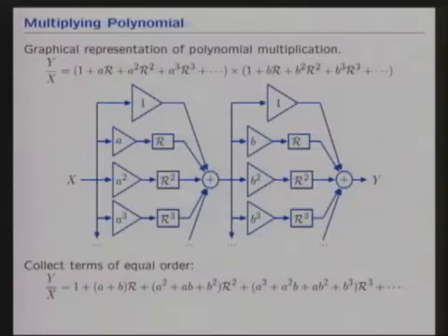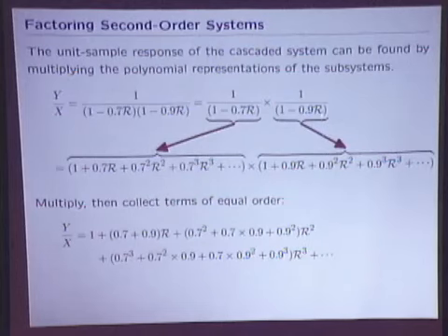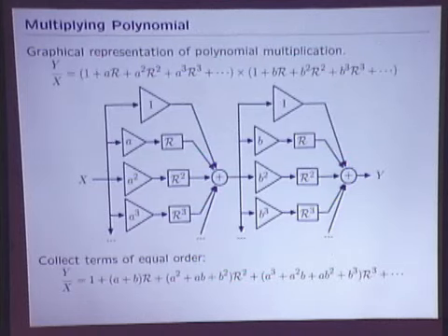The only difficulty here is bookkeeping, not missing a term, so there are graphic aids to that. Think about the block diagram that would correspond to the infinite feed-forward realization of the left part, and the infinite feed-forward realization of the right part, right? So I'm thinking about this system and that system being represented by this infinite system and that infinite system. And now I'm just making a block diagram realization of this and a separate block diagram realization of that, and cascading them to get this. And now the bookkeeping is trivial.